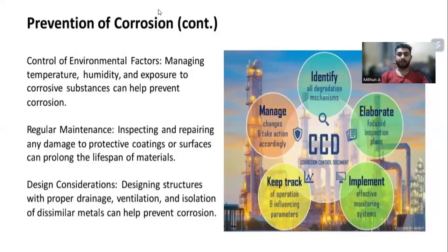Regular maintenance, inspecting and repairing any damage to protective coating or surfaces can prolong the lifespan of materials. Design considerations: designing structures with proper drainage, ventilation, and isolation of dissimilar metals can help prevent corrosion.